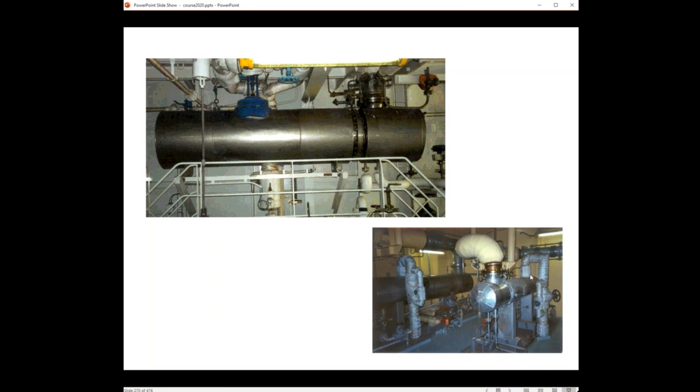So you will send liquid inside the forced vaporizer, and the cargo vapors coming out are then sent to the boilers for propulsion purposes. And in that way, you have sufficient vapors available to maintain full speed.